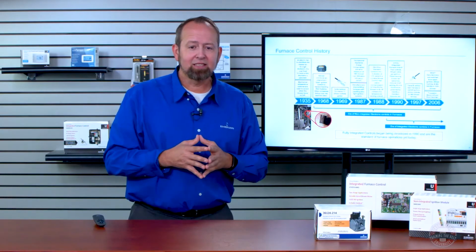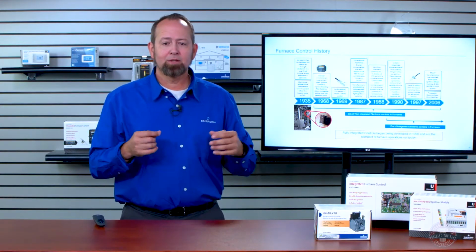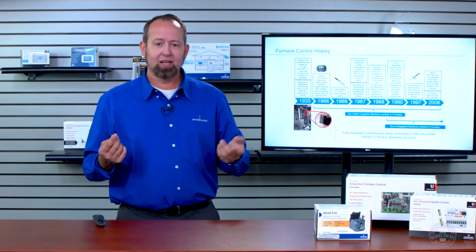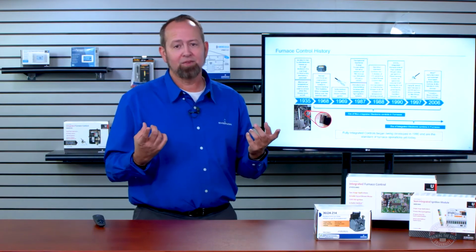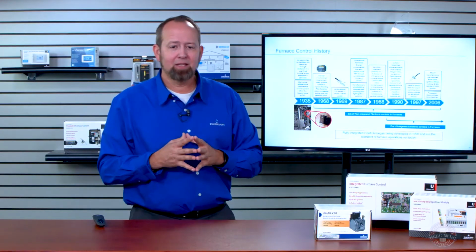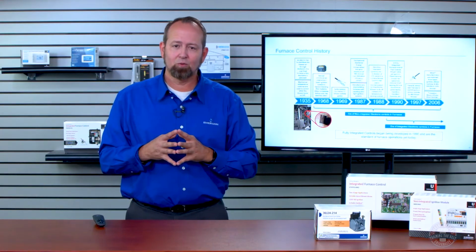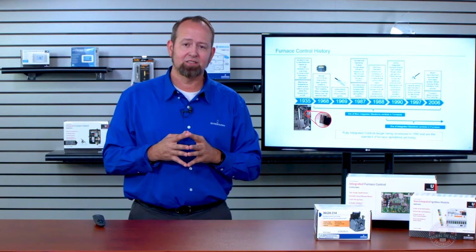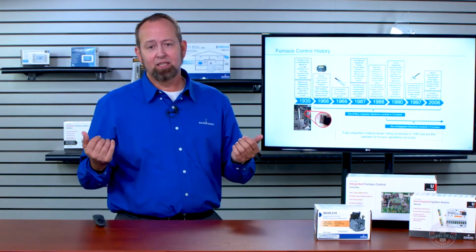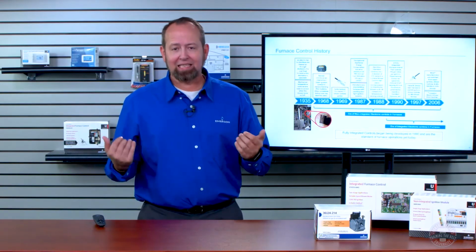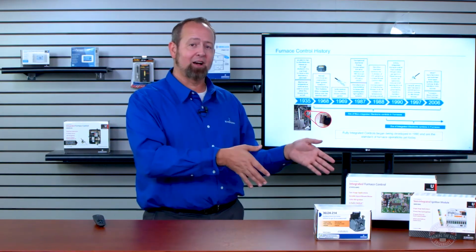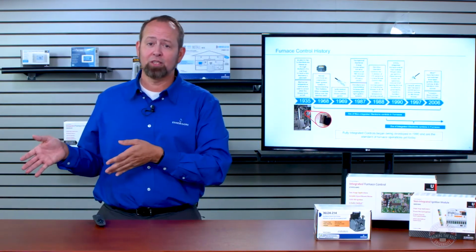Then in 1969, carborundum, silicon carbide, came out with an igniter. So now we had the option of spark or a type of hot surface ignition system. Then a big step in 1987, when federal regulations said no more gas furnaces below 78% efficient. In other words, at least 78% of the heat produced by that gas needed to go in the house. 22% could go up the flue.